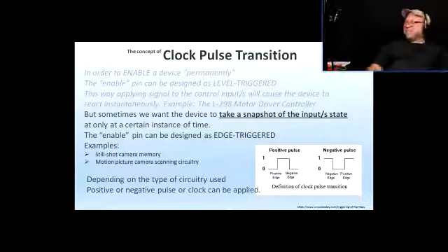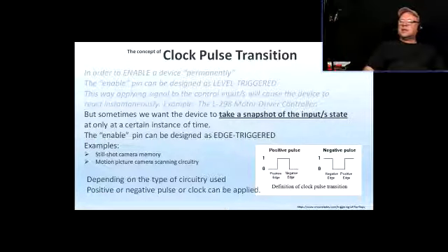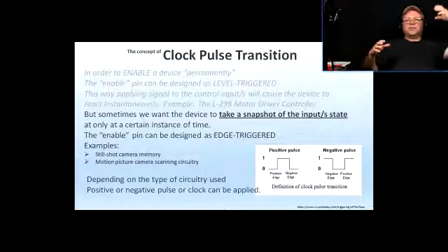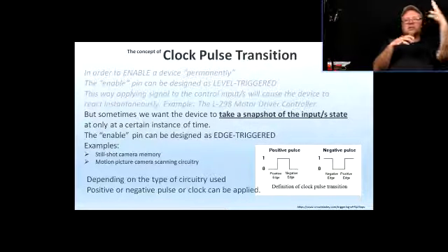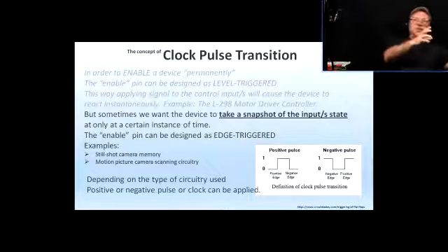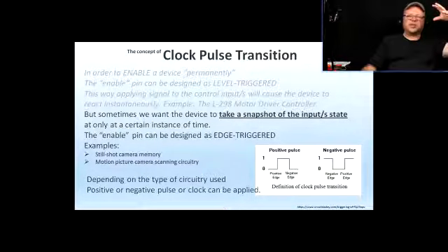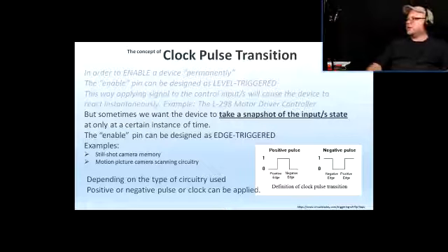But any of your stuff that's going to be motion activated is going to be a momentary interaction that has a progressive delay after the fact, right? Like you said, if you walk past a motion sensor, it triggers. Whatever it reacts after the fact is built into the circuit. Like you said, it latches. Yeah. If it did not have the latching circuitry, then the light would flicker on and off, because the motion sensor sees your infrared energy, and as soon as you step out of it or stop moving, it's going to turn off. So it'll be just flickering on and off, and so then the timer is engaged. Okay, once you see that, turn it on for like 30 seconds or so, right? So there it is.